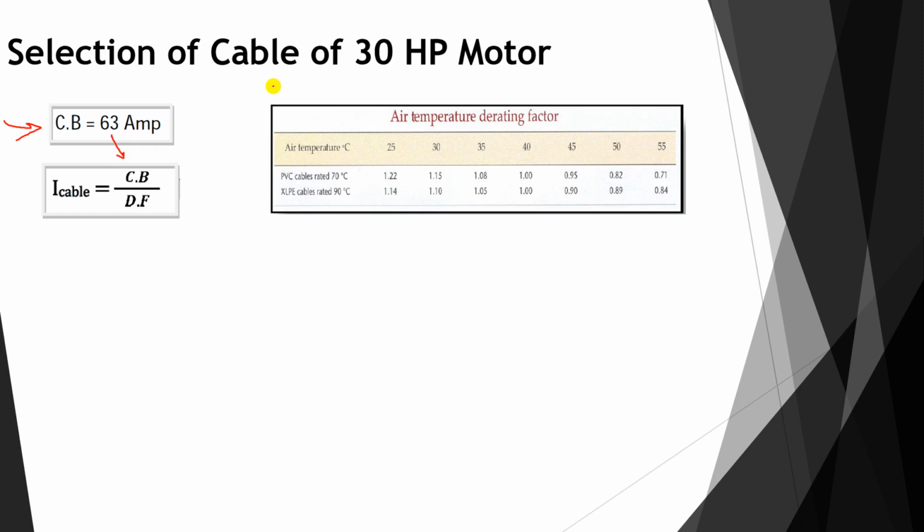First, in this example, we said it is in conditions of 50 Celsius degree. Okay, so this is the first point. The second point is that it is not buried in the ground. It is on a cable tray, which is in free air. In a cable tray there is a distance between cables, which means the grouping factor is 1, or unity. The cables are not affecting each other because there is a distance between them.